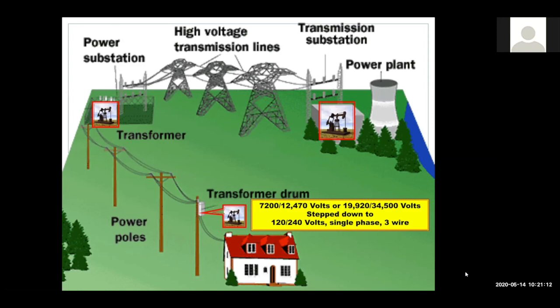Well, if you get in the middle, if you get in that circuit anywhere, and it goes through your body, you're going to get a shock. And right here, before we go too much further, remember, guys, any voltage that we're looking at on this slide is multiplied times 1.414. And that's the peak voltage.